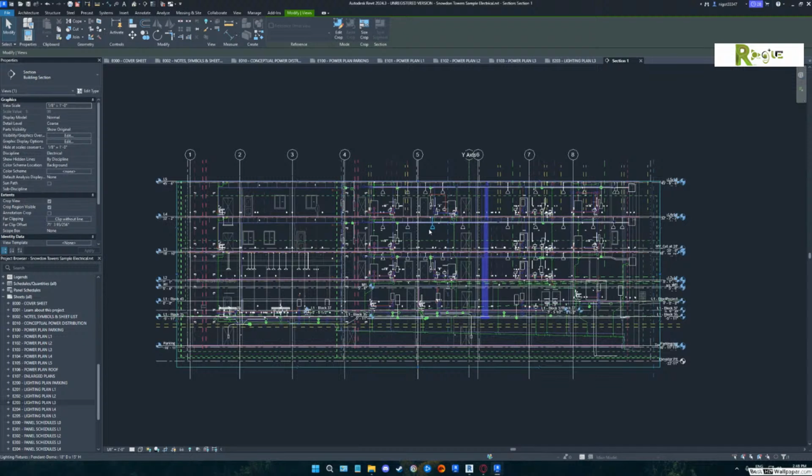The idea is to have non-active grids and levels, and then you make the filter say, if it's in the HVAC drawing, turn everything off that's not an HVAC grid or an HVAC level. If you're in the plumbing file, you make it say not the plumbing stuff. Does that make sense? Yeah.